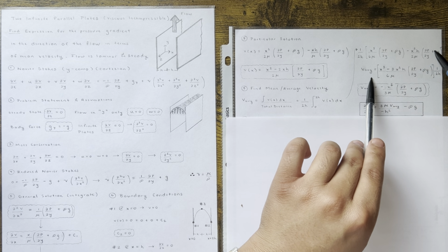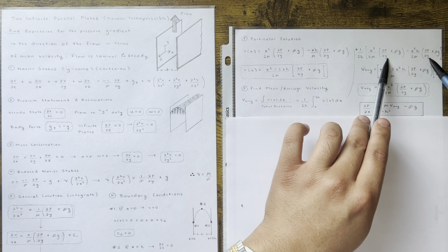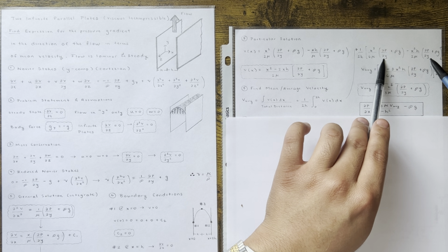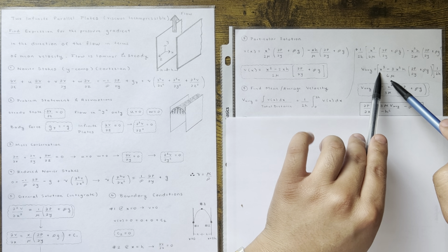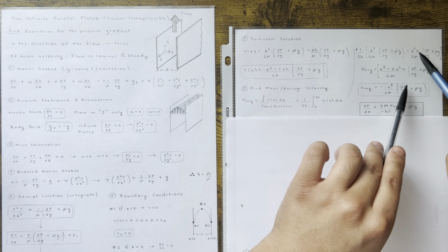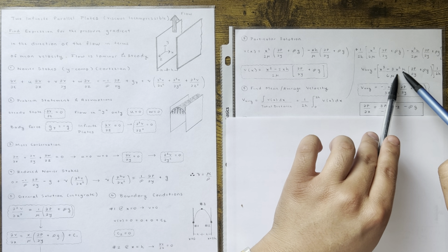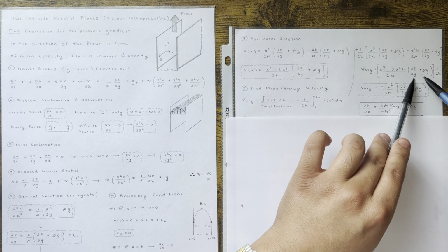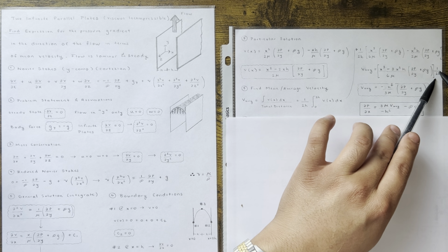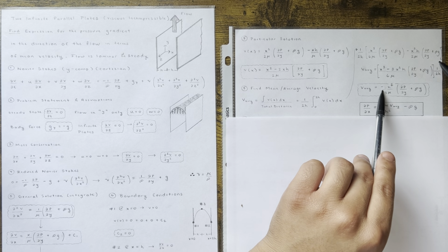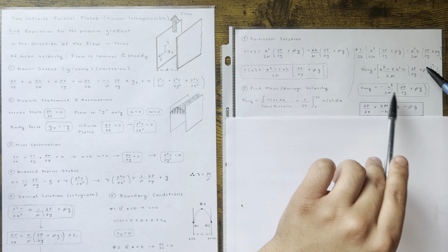Now what I did was I just combined the terms, right? These two terms, because they both share the same constant to multiply it to. So in this case, I did x cubed over 6 mu, which is that term right there. And then this one I had to multiply by 3 top and bottom to get the 6 mu at the bottom. So you get negative 3x squared h. And then times a constant, and then again times 1 over 2h, okay? So here. Simplify this, and you will get negative h squared over 3 mu, okay?